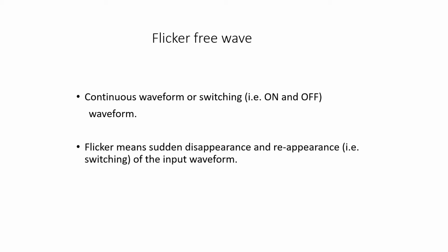When an AC voltage, for example a sine wave, is applied to the vertical deflecting plates and no input is applied to the horizontal plates, the spot on the screen moves up and down continuously, that is, vertically. A ramp waveform applied to the horizontal deflecting plates of an oscilloscope causes the electron beam to be deflected horizontally across the screen, that is, left to right and right to left.